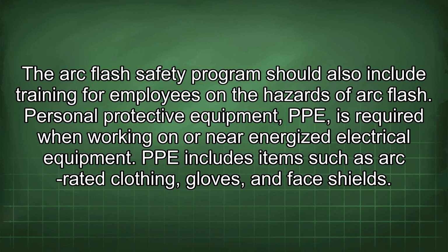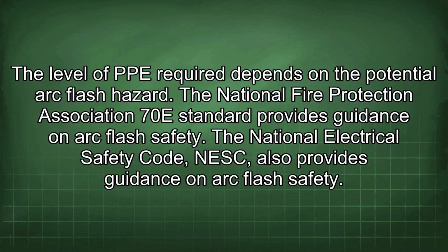Personal protective equipment (PPE) is required when working on or near energized electrical equipment. PPE includes items such as arc-rated clothing, gloves, and face shields. The level of PPE required depends on the potential arc flash hazard. The National Fire Protection Association 70E standard provides guidance on arc flash safety. The National Electrical Safety Code (NESC) also provides guidance on arc flash safety.